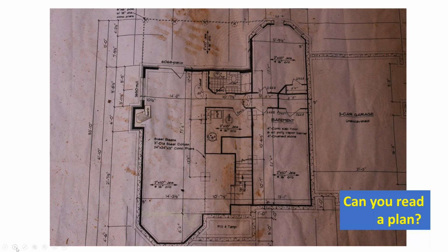Also, most plans are built for framers, not for bricklayers. So the framing is going to be a different dimension because ANSI requires all the measurement be on the outside, which means you're going to take into consideration that brick wall on the exterior as well. So it's going to add a little bit all the way around to your floor plan.